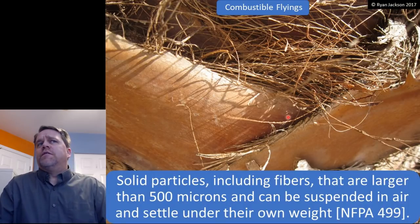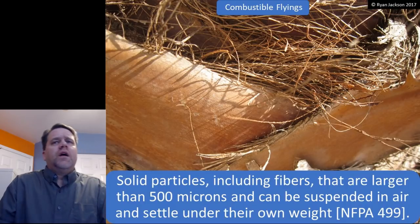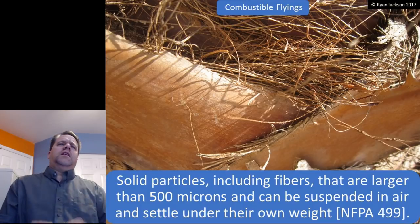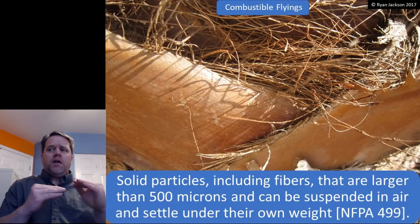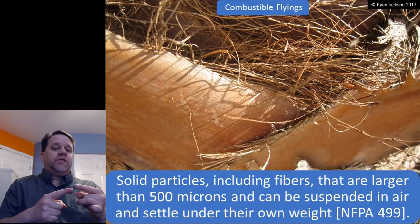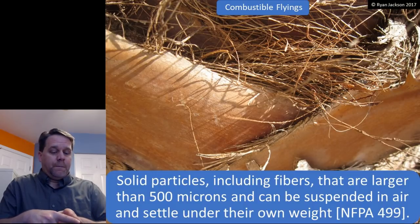So combustible flyings, and this is wood shavings here that we're looking at, are solid particles, including fibers, that are larger than 500 microns and can be suspended in air and settle down under their own weight. In my opinion, because we have this 500 micron measurement, if you have a combustible solid and it's smaller than 500 microns, we call that a combustible dust.